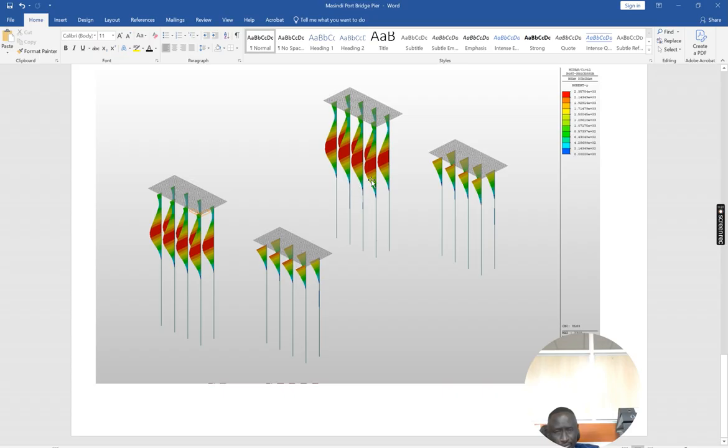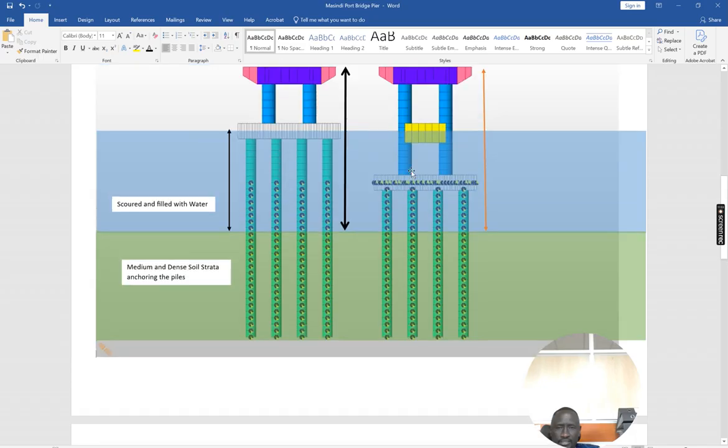So it's always not good to say, okay, since moment ends here, we cut it. No, because you have three forces here. Actually, you have the bending moment along here, then you have the shear force, then you have the axial. So these are bending moment. Definitely, if you look at what happened here because of lateral load and then fixity is at this point